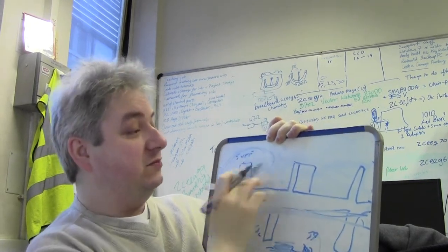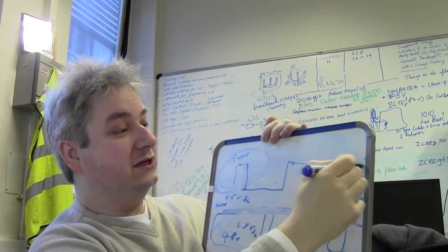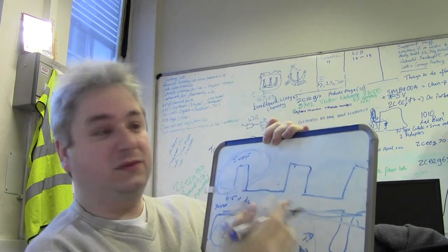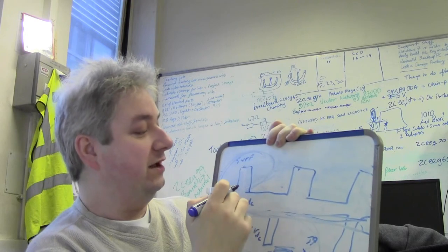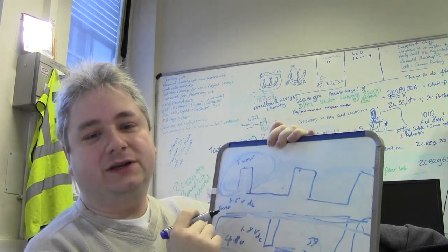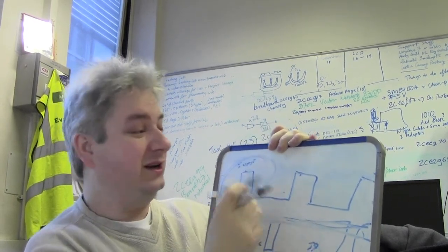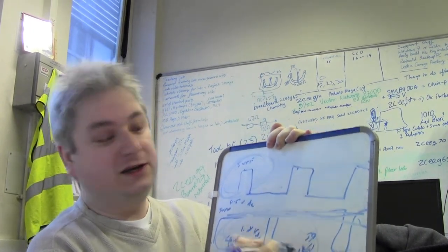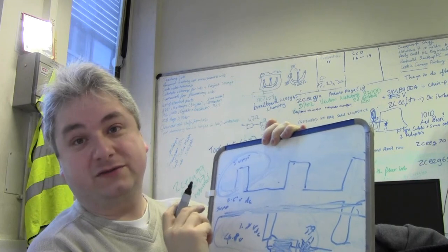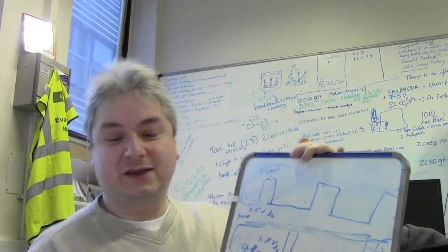And that's perfectly fine. But if your microcontroller throws a brain fart or something, and starts outputting your mark to space wrong, or your pin goes high for a long period of time, you can end up knackering your LED. So it's always good practice just to shove that resistor in, and that's all I'm going to say about that,